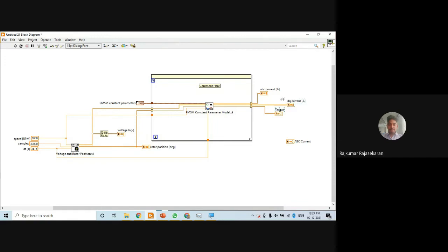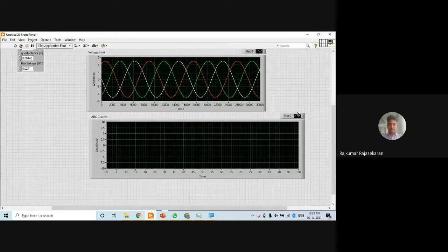Again, during visualization also, we need to do something called transposing, because that's how the data is coming outside from this function. Visualization in LabVIEW follows a row-wise visualization, so this gives a column-wise output. We'll just transpose it to get the data.